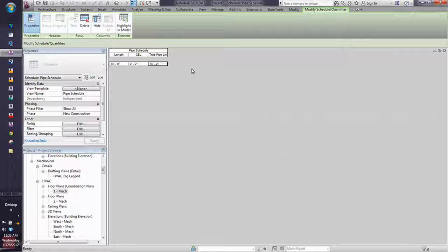When you do an alignment, you align it by picking the edge of the wall first, then you pick the back of the fixture, and then you lock it. You do an alignment and lock it. Up until a certain point, that's where we ended up doing the copy monitor trick, where you can copy monitor wall-based families.